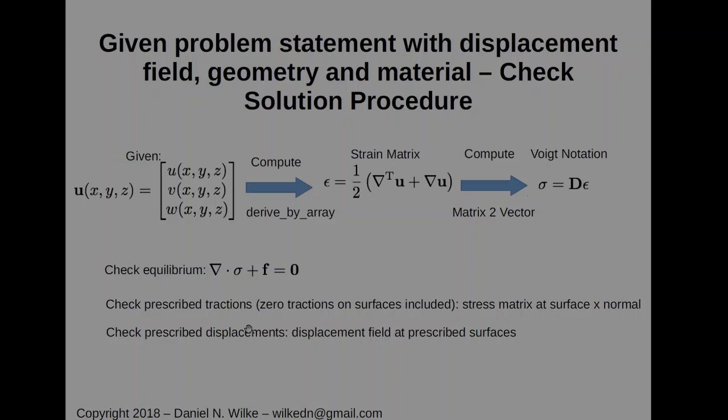Okay, so I will make this point clear when we look at the strong form again, but just as a reminder, when I have a structural mechanics problem, wherever I have a prescribed displacement, there will be a traction that will follow there. So to enforce that prescribed displacement, some force is going to be required.